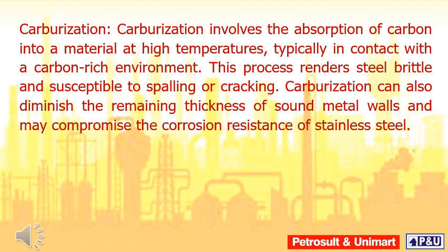Carburization. Carburization involves the absorption of carbon into a material at high temperatures, typically in contact with a carbon-rich environment. This process renders steel brittle and susceptible to spalling or cracking. Carburization can also diminish the remaining thickness of sound metal walls and may compromise the corrosion resistance of stainless steel.